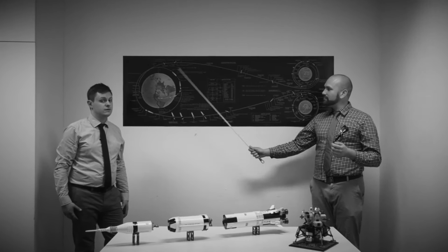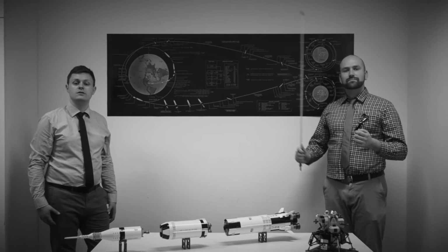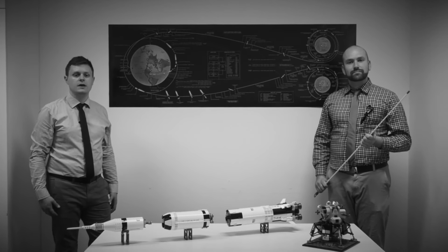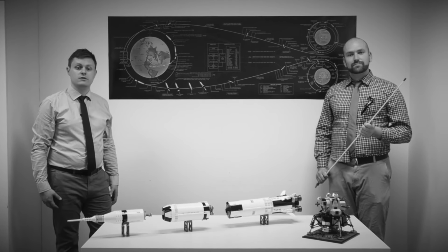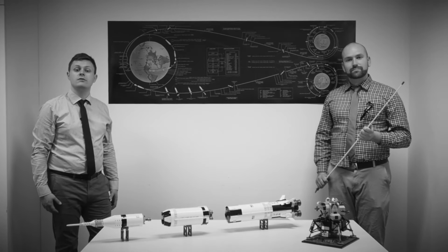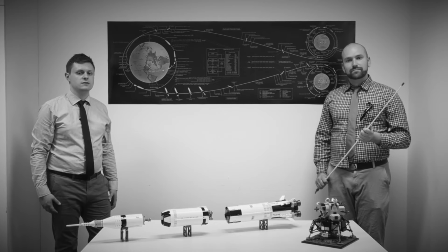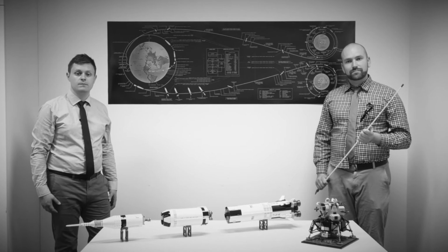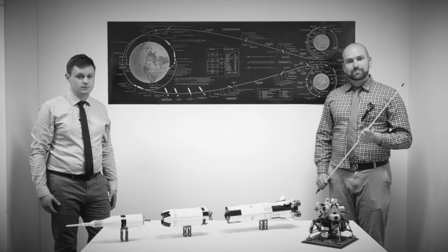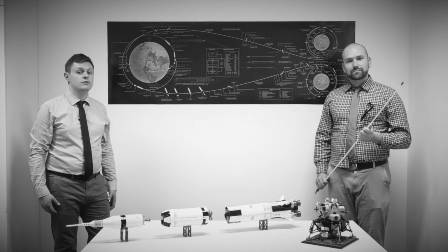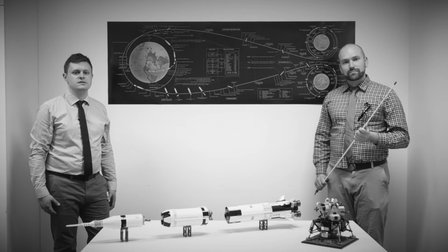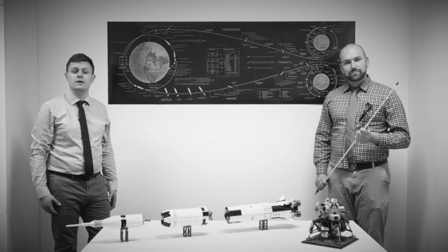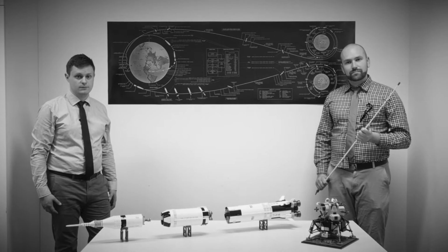Before liftoff, the flight's backup crew is in charge of powering up the spacecraft, including the Apollo guidance computer. Several self-checks are completed by the computer to ensure its readiness, including checking the integrity of the core rope memory, where all the programs are saved. Now the first program, Program 1, is activated to initialize the inertial measurement unit. The AGC then switches to Program 2, waiting for liftoff.